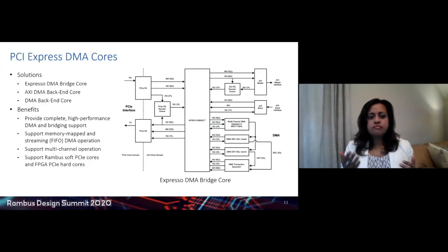It supports memory mapped and streaming DMA operation, supports a large number of DMA channels, up to 1024 channels, and it also provides support for multifunction SRIOV operation as well. Now, we also do offer DMA drivers that are companion to the DMA cores, and we support both Windows and Linux operating systems as part of our drivers.